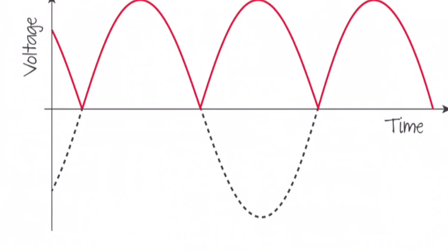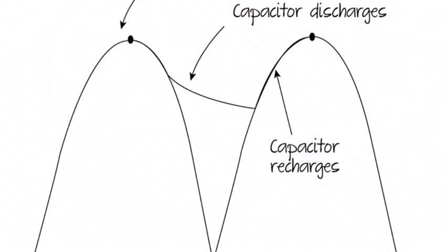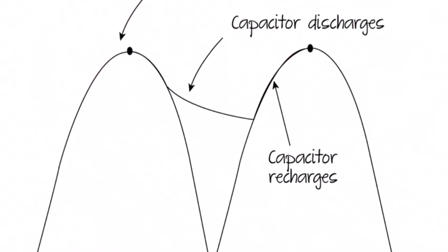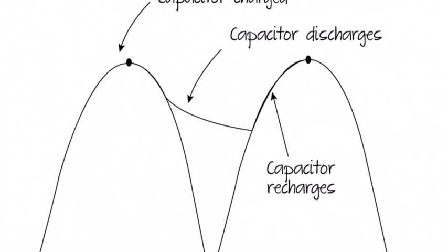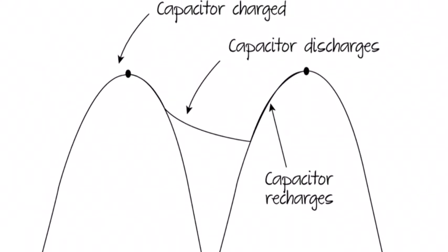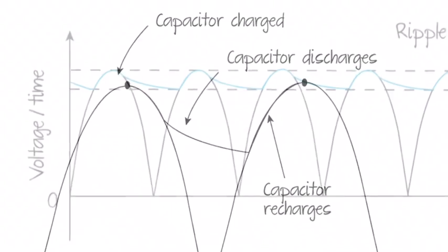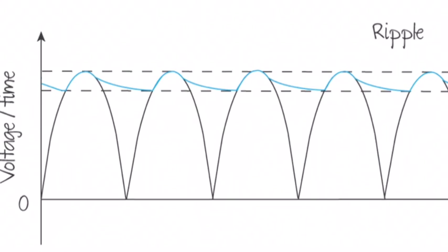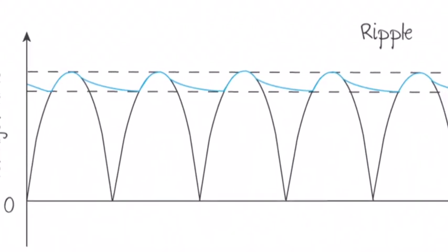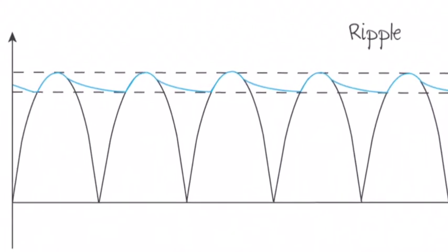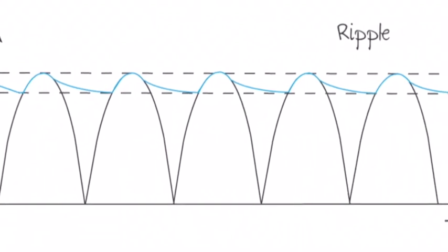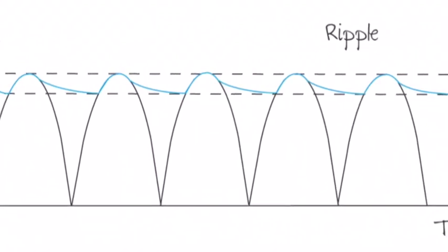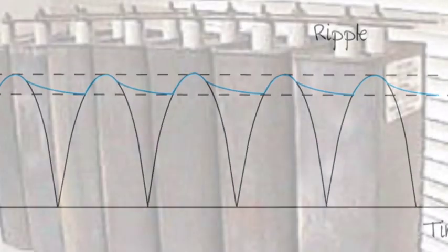Reason why? We see the option of adding capacitors. To make the optimal AC to DC transformation, we should add capacitors to the circuit, as these act as a temporary battery which later discharges exponentially. So, as the capacitor charges in the peak, it then discharges exponentially and fills up the gaps in the full-wave rectification, resulting in DC with a slight ripple. To decrease the size of the ripple, one can use a larger capacitor or use a load that draws a smaller current.